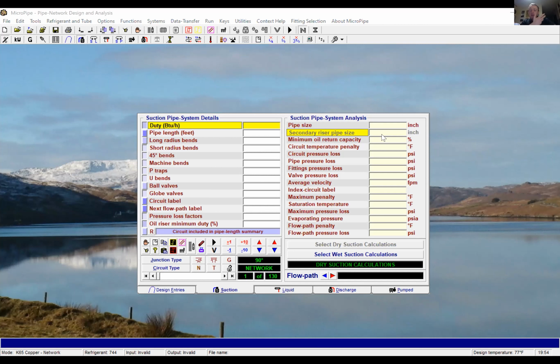There's not; that's governed by the largest pipework, which is 6-inch within MicroPipe. Okay, so 6-inch. That's quite a size. That's on a distributed system, Trevor. We can go larger if we're talking a cascade, if we're actually pumping a fluid, if it's a secondary system, whether it be CO2 or a glycol. Okay, excellent.